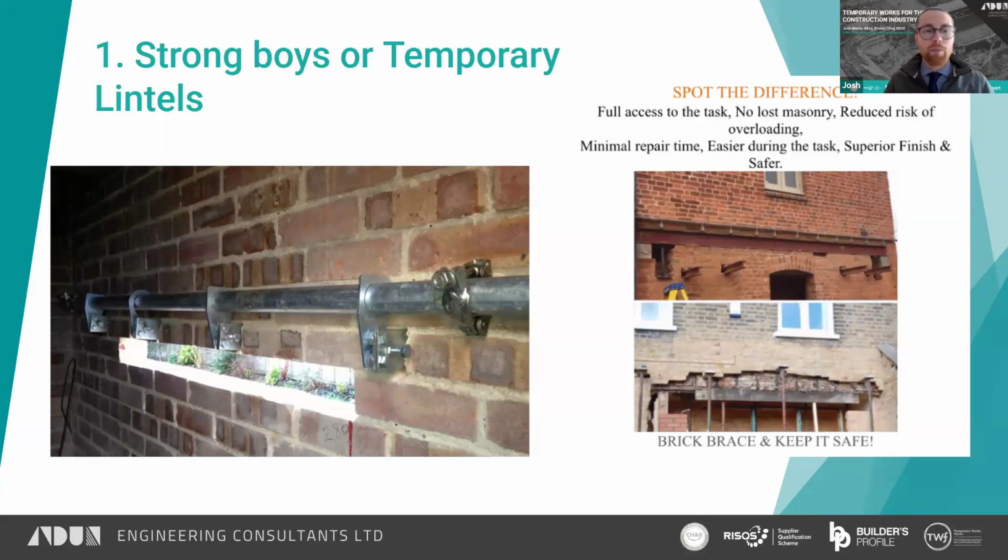Then when you open up the brickwork underneath, it acts as the wall above as well as that kind of compression strip at the bottom, which then remains in compression because it's kind of been pre-tensioned up. It's a pretty clever system. It's not something I've used, I've specified it, and then it wasn't quite suitable for that application.